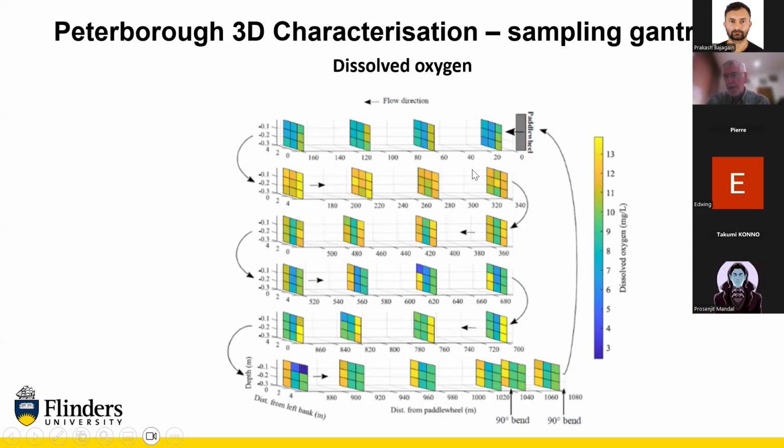It was placed round about here in the pond, on the second channel. We took measurements from that static point and then compensated for the change over the day when we were doing different time measurements during the day. We had to have a set point to enable us to take into account the diurnal variation.